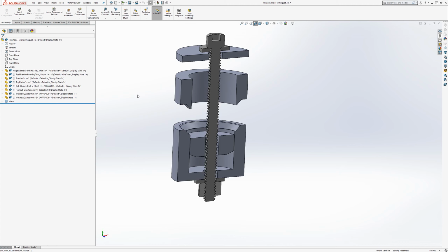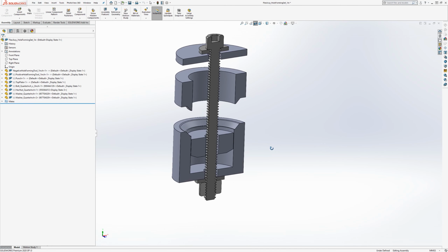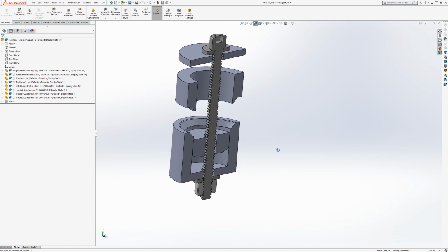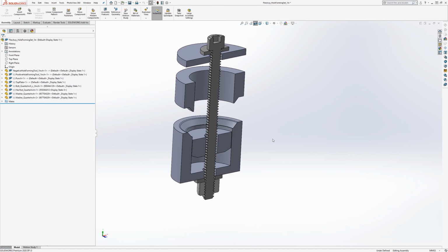If we go back to this flexible assembly and just press Control Q to update everything, now it realizes that, okay, I can sense that the context that is generating these parts is up to date and the references are open, so that question mark goes away. So that's an example of using a top-down assembly approach to create the shape of parts in an assembly.